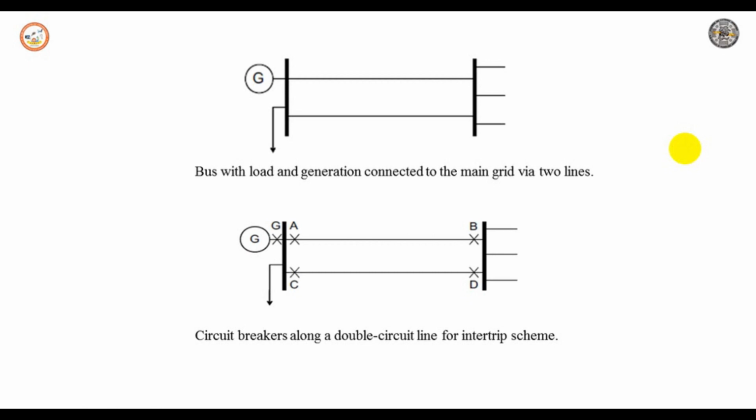The design criterion for an operational state is that the loss of a component should not result in any overload anywhere in our network. Most network operators do not perform calculations for all operational states and for all component losses. Instead, a limited number of operational states are considered, typically including maximum demand and minimum demand. Prior knowledge about these critical operational states is needed.